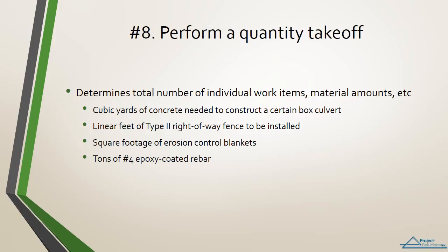Number 8, perform a quantity takeoff from the plan set. The quantity takeoff, or quantity survey as it's sometimes called, provides the backbone for the detailed construction estimate. The quantity takeoff is where estimators determine the total number of individual work items to be completed, total amount of construction materials needed, etc.